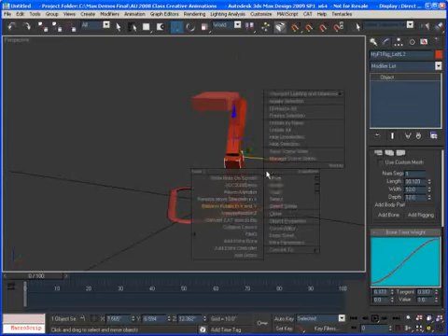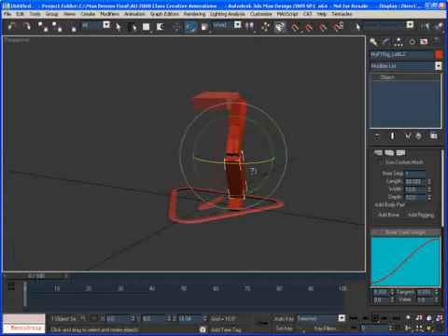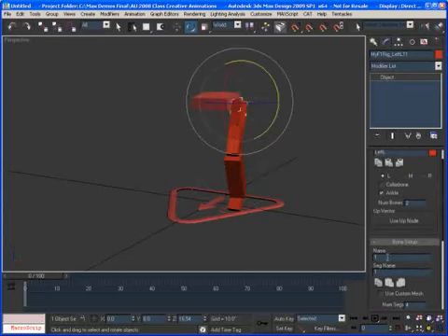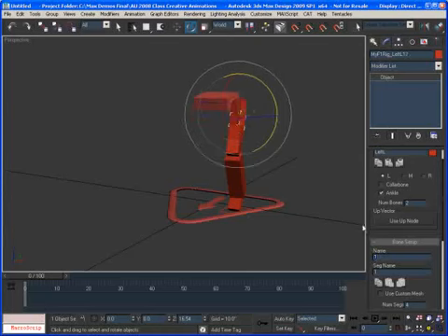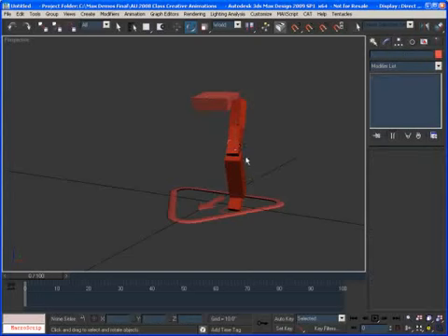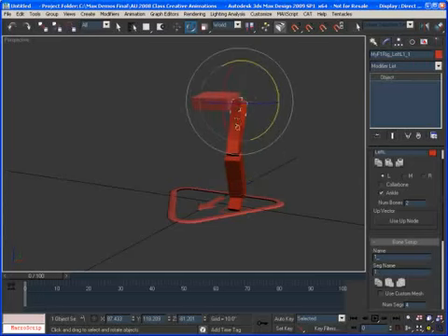Now you'll see that if I grab this bone and I rotate it, we get some nice twisting over there. And if I grab the actual twist, you'll see that this is part of bone number 1. This is segment number 1. So if I grab this here, it's still part of bone number 1, and it's segment number 2. And you see that as I grab them, all of these here are named automatically. If I want to have an underscore here after the 1, I just need to put an underscore there and press enter, and I just deselect and reselect. You'll see that now I've got an underscore if I want that to be renamed automatically.